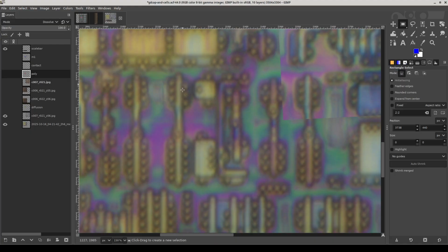And it looks like we've got another inverter here and another inverter here, but these, we can see the transistors are a little bit larger. The NFET is 3 contacts high and the PFET is 5. So this is presumably a higher drive strength version of the same cell compared to this one. So we could somewhat arbitrarily call this an X1 inverter and this an X2.